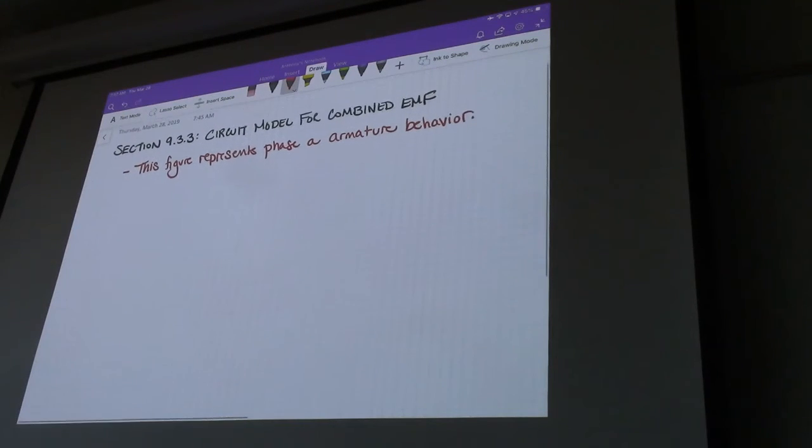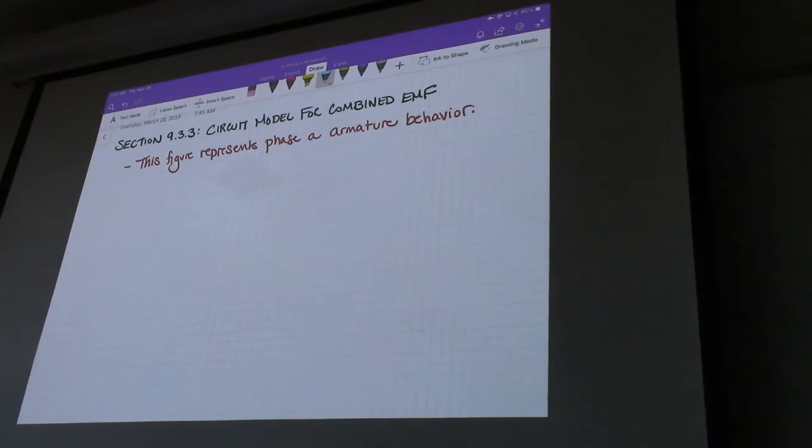So what we have, and we'll go back and explain each piece along the way, is an internal voltage, which we're going to call EAF, in series with a value that's XM. We just defined what that value was. That's our magnetizing reactance. That's also going to be in series with another reactance value, which is going to be XL. That's going to be our leakage reactance.